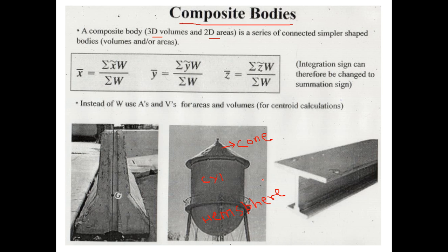But please note that all these three shapes are simple shapes for which we have well defined formulas available for their centroid, and if they are made up of a single material, then centroid, center of mass, and center of gravity remain the same, because in engineering our structures and designs are basically on the earth, so the gravitational field is uniform, unless you are designing something that needs to go out in space. In that case, the gravitational field can vary, but mostly the structures are under a uniform gravitational field. So this means that if you can calculate the centroid of this entire body, you have also calculated the center of gravity and center of mass, provided that all these simple shapes are made up of one material.